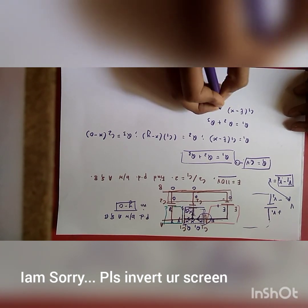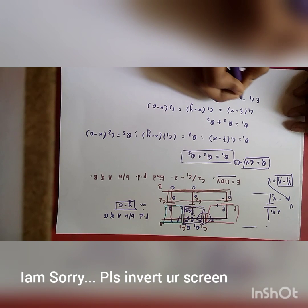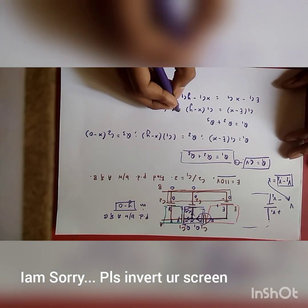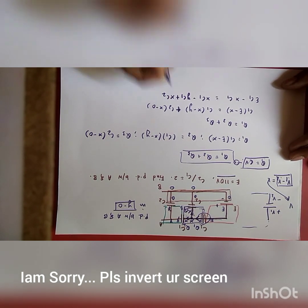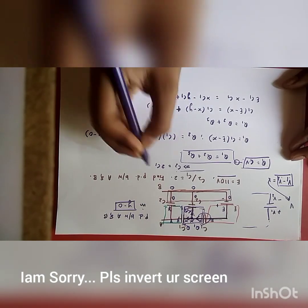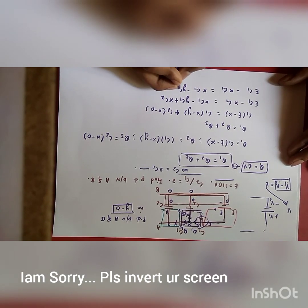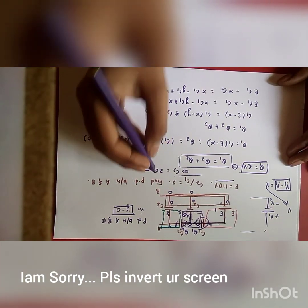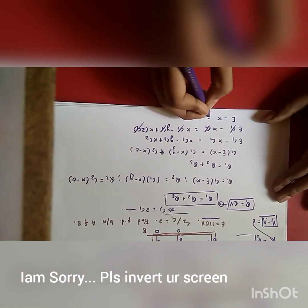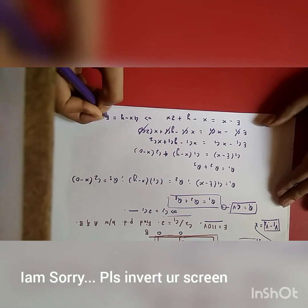C1 into E minus X equals C1 into X minus Y plus C2 into X minus 0. So E C1 minus X C1 equals X C1 minus Y C1 plus X C2. It's given that C2 by C1 equals 2, so we can conclude C2 equals 2C1. Substituting this, EC1 minus XC1 equals XC1 minus YC1 plus X into 2C1. Now cancel all the C1 out. That makes things easy. E minus X equals X minus Y plus 2X. If you simplify the equation, you get 4X minus Y equals E. This is equation number 1.